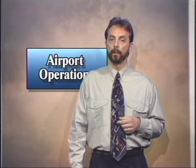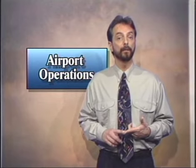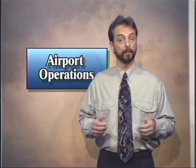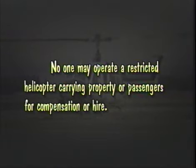Let's look at some general operating rules. When we speak of a category of aircraft, we mean a grouping of aircraft based on intended use. A restricted category aircraft is certificated for a special purpose, such as aerial spraying or banner towing. It's important to remember that no one may operate a restricted category helicopter carrying property or passengers for compensation or hire. The only time another person may be carried on board a restricted category aircraft is when they're a required crew member, a crew member trainee, or they perform an essential function.